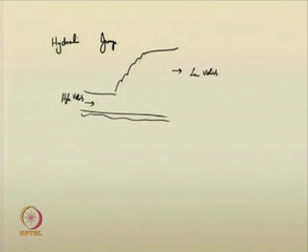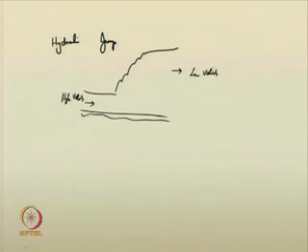So, what is it actually doing? When water is coming with a high velocity, it has a high kinetic energy, and when it is going out with a low velocity, some energy is getting dissipated. This dissipation of energy can be beneficial for fluid flow in channels.